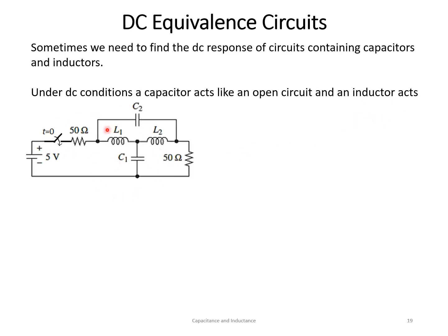So here is a circuit, and this is a switch. We will discuss this in many circuits in chapter number 7. The switch is initially open, due to the sign; look at this arrow over here. The switch is open initially for a long time, such that there is no energy stored in the capacitors and in the inductor, and the voltage and current, everything is zero.